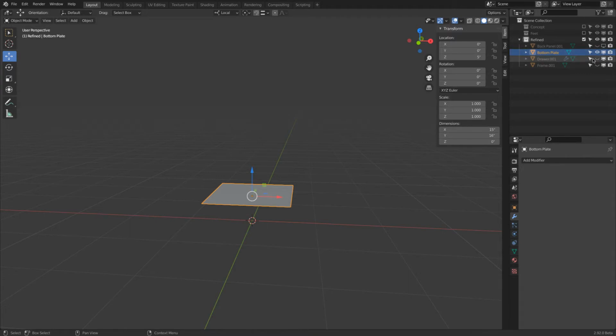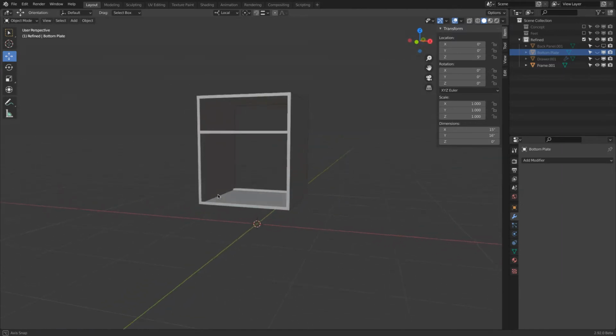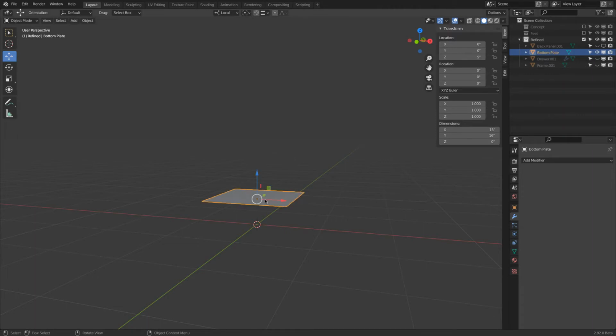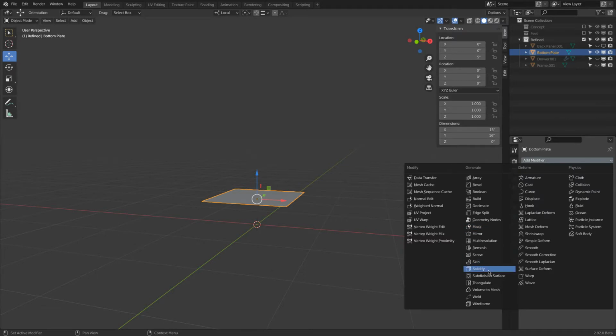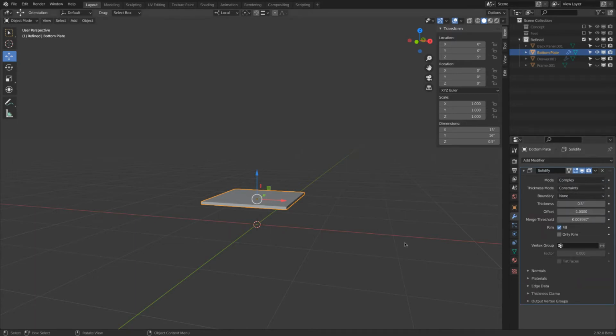And just for reference again, you see this sits on top. When we only take a look at our frame copy, there we can see how we disconnected this face via the separation command and turned it into its own object. The reason why we did this, we can select this face, go modifier, solidify, 0.5, complex is fine. Yeah, and that's it.